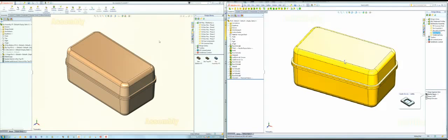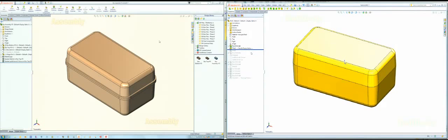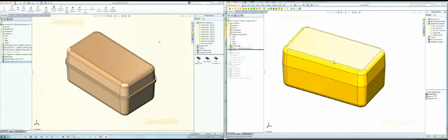First, we're going to cut out the recess with a library feature, and then we're going to add a part into this part. Okay? But we have to get it before the shell because we want our recess to be before the shell. So I'm just going to roll back before the shell, and I'm going to find our library feature, and it's this recess right here.